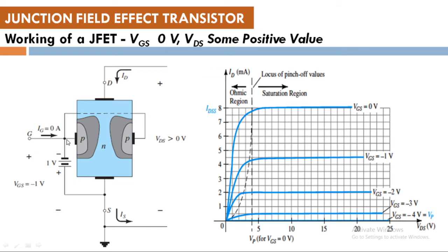So when we are providing a negative potential at the gate before we are providing any potential at the output, you can see there is already an increase in the depletion region at the top. This is because at the initial stage itself you are providing sufficient negative bias to this P and N region, which is actually increasing the depletion width before we can provide the output voltage.